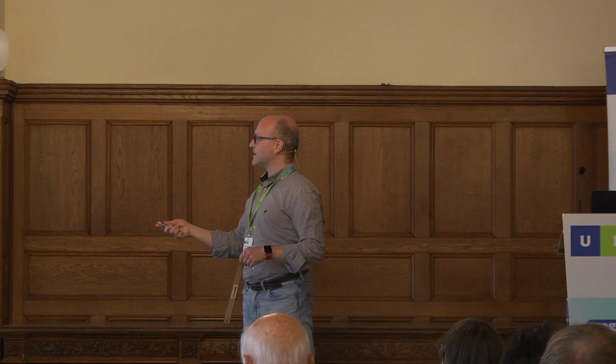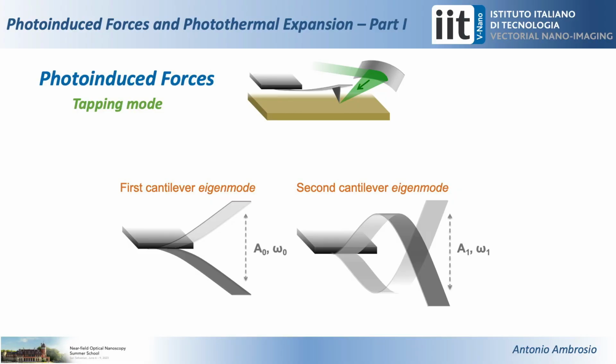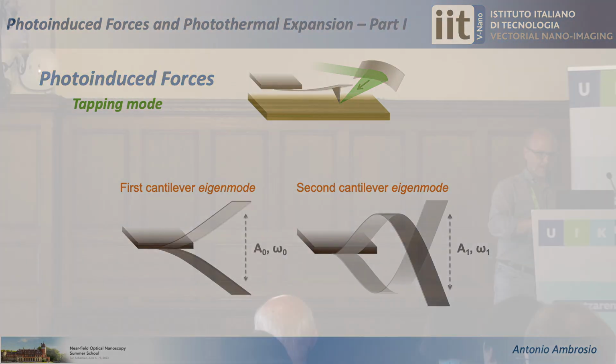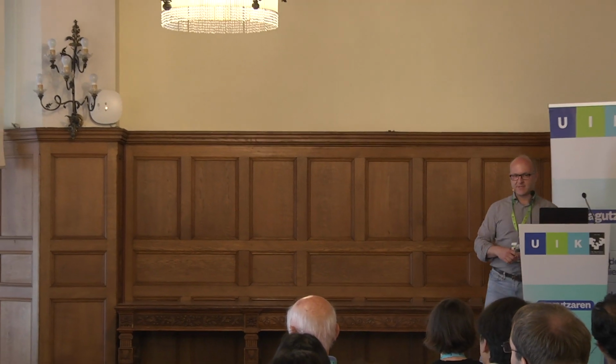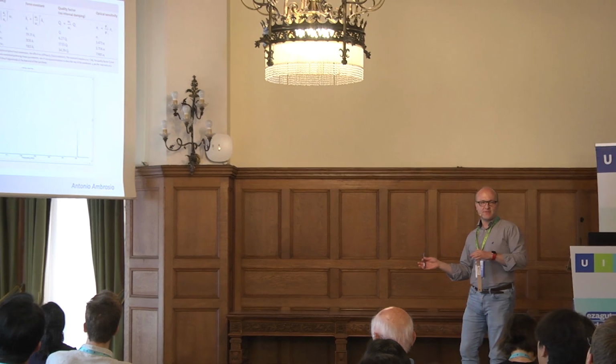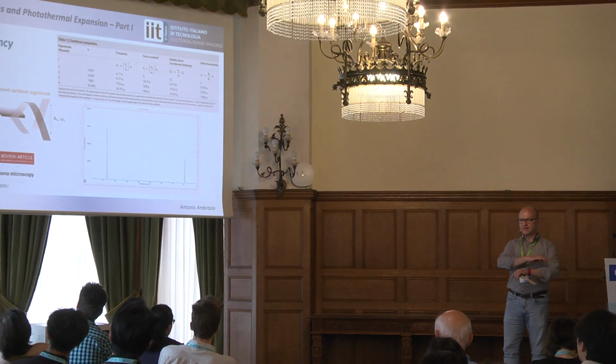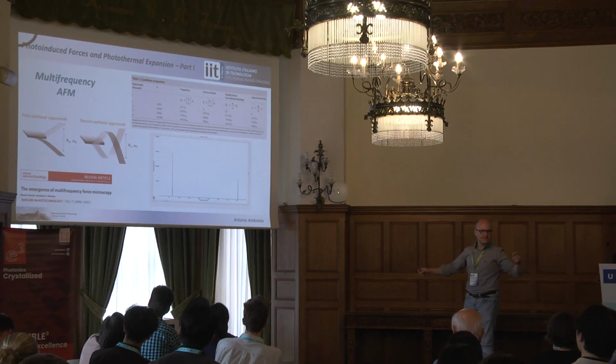So again, we have infinite eigenmodes, but let's stop at the first two. This one goes up and down, and this one has a node in the center. It is the second eigenmode sketched here. And they have two different frequencies, and never be confused between eigenmodes and harmonics. They are two different words, right?